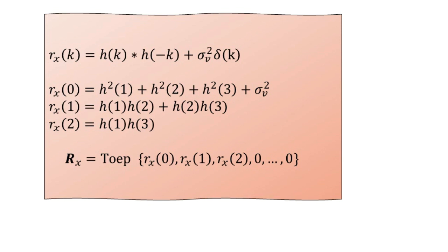Now let us have, for example, the upper bound, the largest value of the autocorrelation matrix, as the largest row sum for p greater than or equal to 5, denoted by lambda suffix max. Lambda is the representation of the eigenvalue. So for the largest we have lambda suffix max less than or equal to Rx of 0 added by twice Rx of 1 added by twice Rx of 2. For the given values of W, we can make the consideration with certain tabulations that you can find in the textbook.